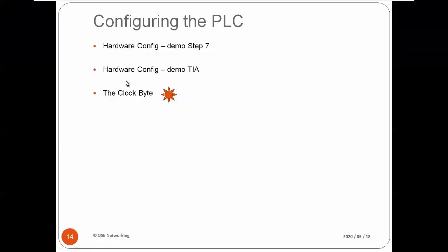It's a very useful feature in Siemens PLC. Now, if I just digress, in Mitsubishi and Omron and some of the other Mickey Mouse PLCs, they have a lot of internal system bits and bytes which do the same thing, but you cannot read them via the COM. So you cannot see what's happening in the PLC via a remote SCADA or an HMI because they are system bits. So we just avoid them. We make our own clocks, we make our own timers, and we keep it simple.